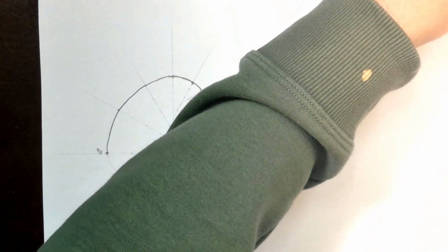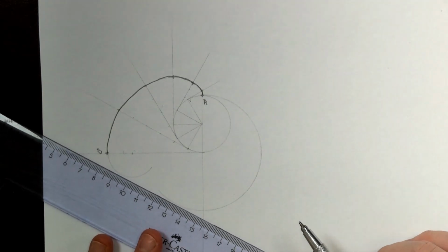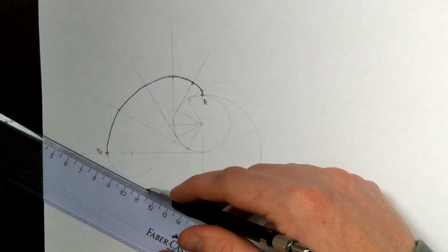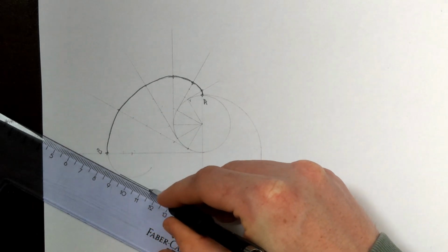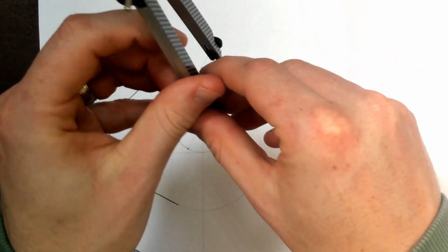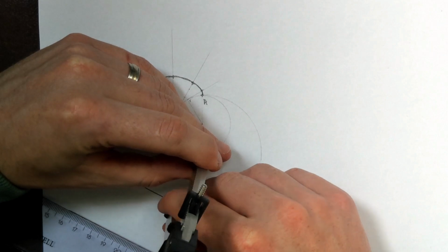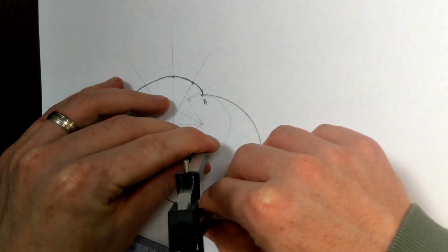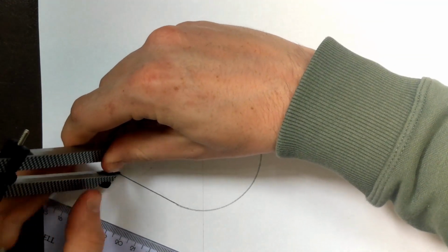Now, the straight section here is just a tangent between the two circles, so the two circular arcs. Now, you're not expected to draw the correct construction for a tangent, so just a straight line that just touches both arcs tangentially will suffice. So it's just there, and afterwards I can darken in my cam. Then I know how much of this radius 15 arc to heavy in as well.